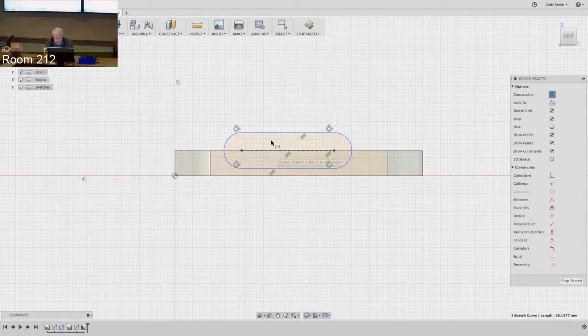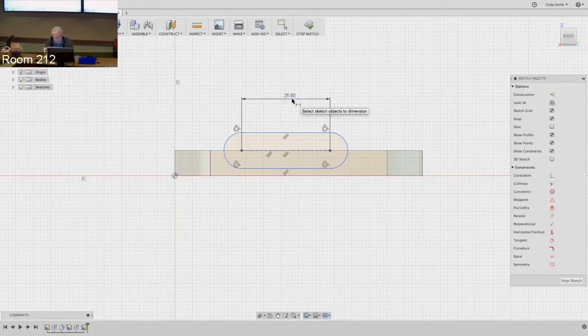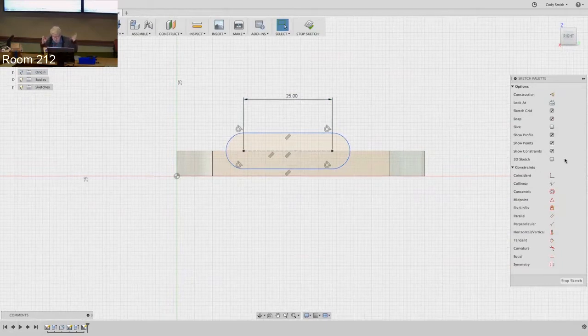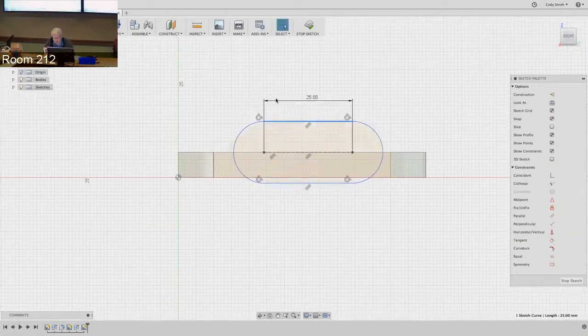So in CAD, in sketch mode, blue lines mean they're unconstrained. That means you haven't sufficiently pinned them down. And black lines mean that they are constrained. So I have to sort of rigidly define every single potential variable here. Like right now, I can make this thing move or be wider. So that's kind of undesired.